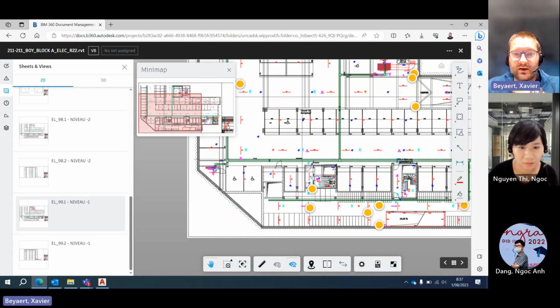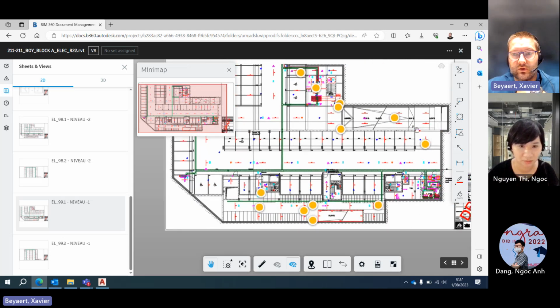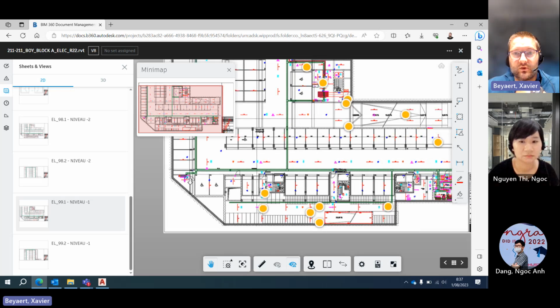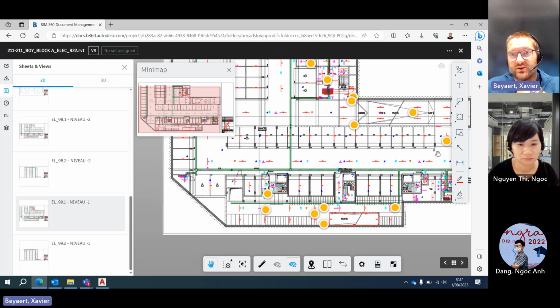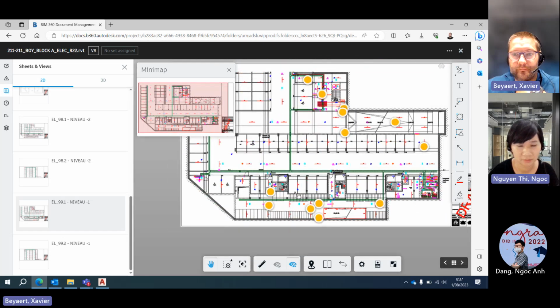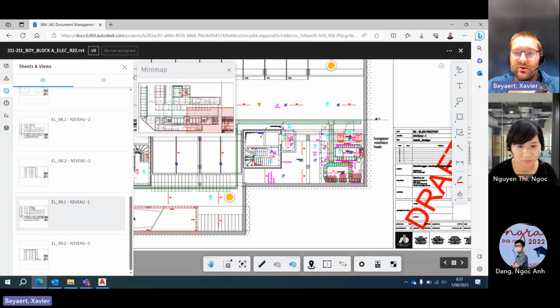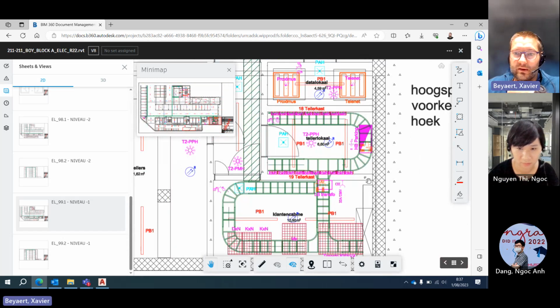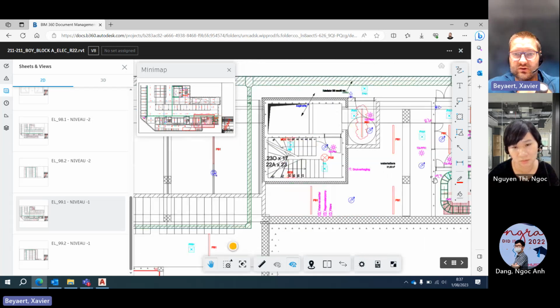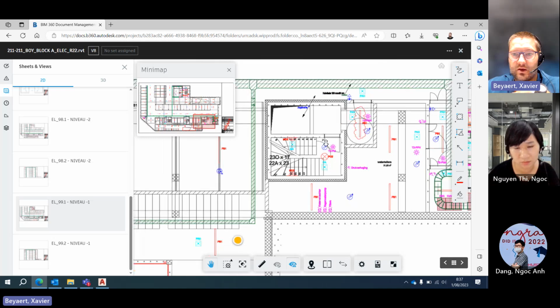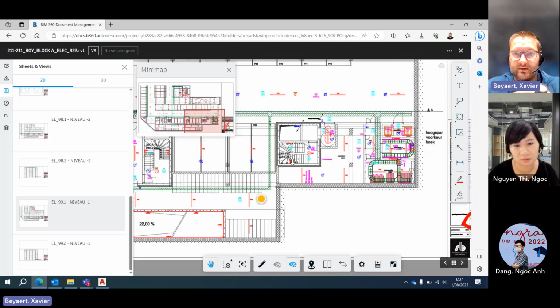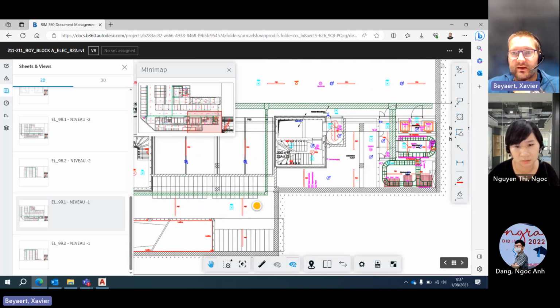Then we have here on the -1 an electrical panel and on the -2, they will provide the feeding for the lighting, one for level -1 and one for level -2. Then, as I mentioned in my remarks, we need another electrical panel here, move that up and put an electrical panel here next to it for the general parts of the apartment buildings. The general parts, I mean the staircases and everything that's above zero.